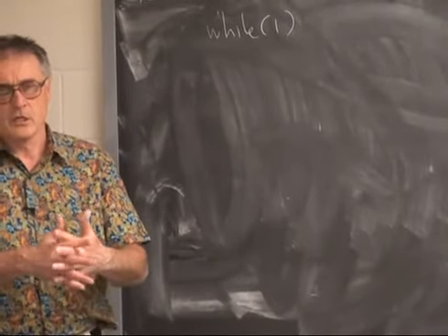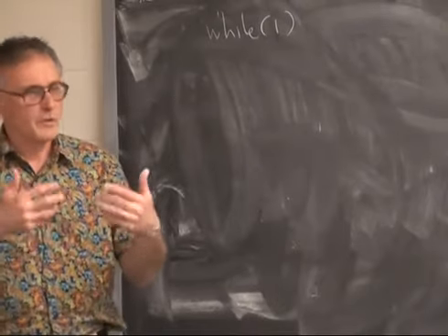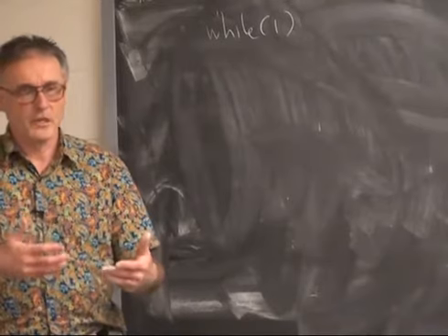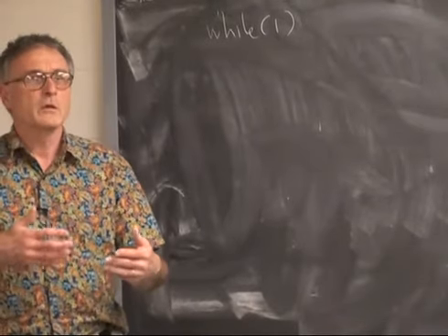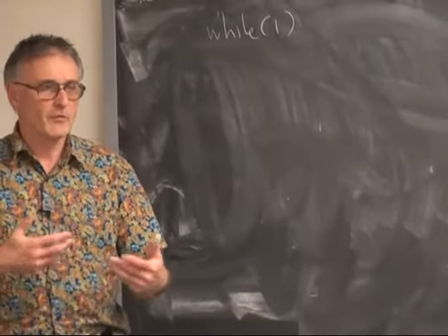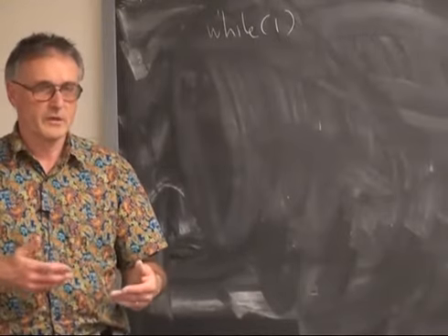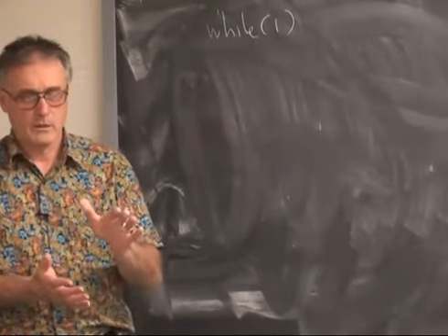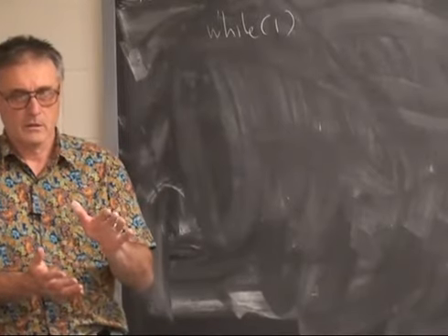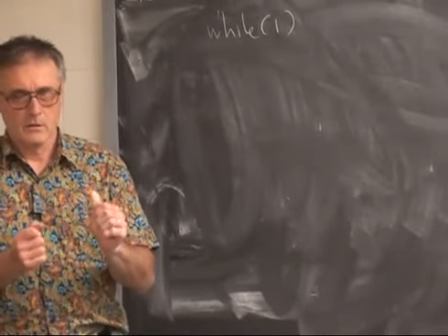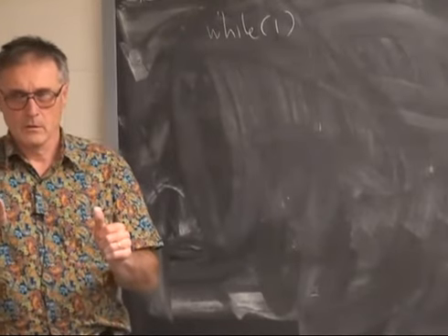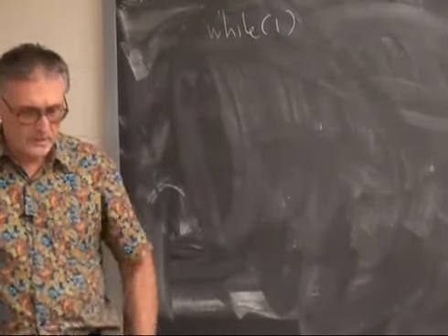You have to instantiate hardware outside of a block. It cannot be used for iteration. Generate blocks should not be considered do loops. They should not be for loops. They should not be considered iterative structures. They are a way of building hardware only. You can nest them, yes.